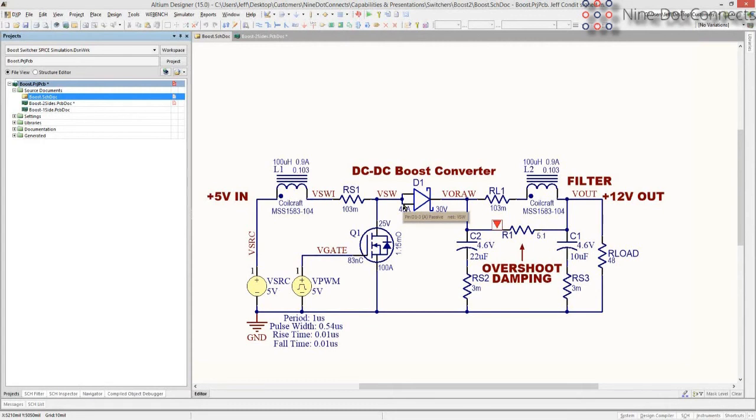One of the reasons for having very well bypassed ground planes is especially on high-speed digital signals. That's normally the subject of this particular topic, but yes, you can have that. What about current change going through the vias? Absolutely, a very rapid current change going through vias. The vias have an inductance, and therefore you will see a large voltage develop across the inductance of that via, and then the current will start to flow, and then it will collapse. So the spikes of vias is a problem. You have to ask, are the switching speeds of the devices in this power circuit going to cause that type of problem? The answer is probably not to a significant degree. You can calculate it, but again, we're down in the neighborhood. Remember, these are huge devices.